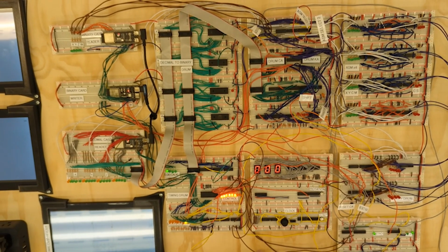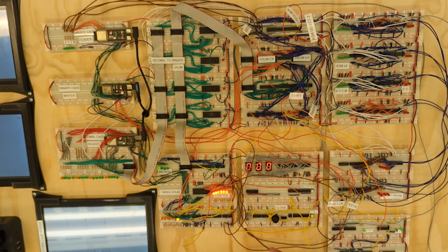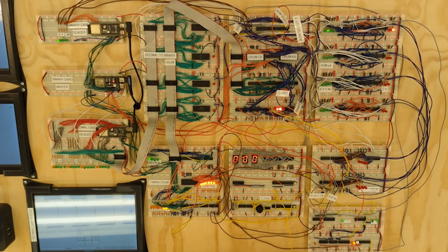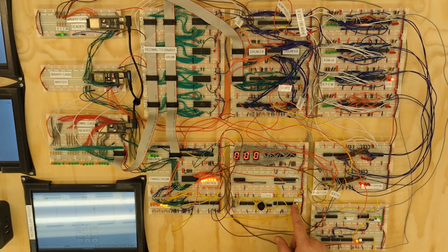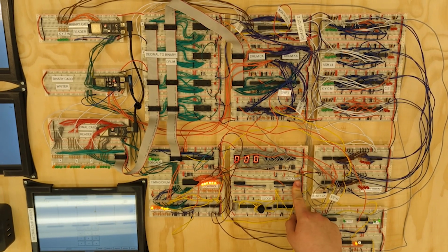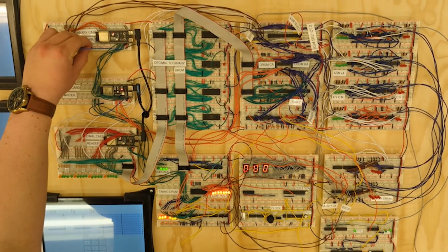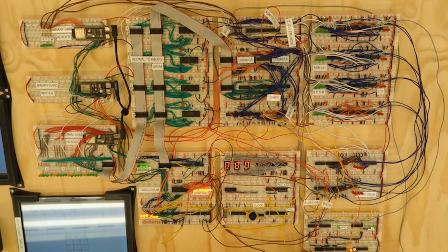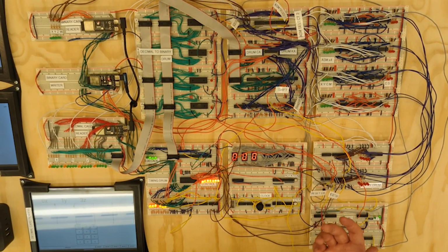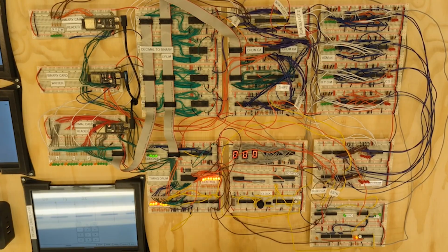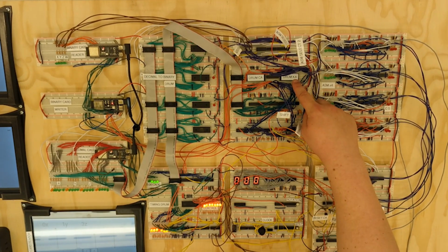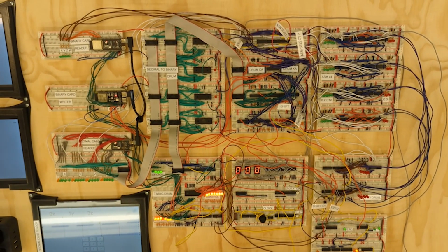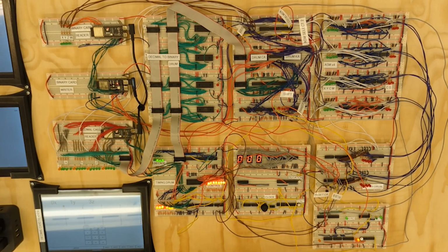We can step through and see that at address 0, we have nothing because none of the numbers have the first bit asserted. But then the second one has this bit asserted for 2, then 4, and then 8. We'll go ahead and disable the module after stepping through the full cycle, reset the inputs, and now we're ready to do our subtractions. So for this reduction, we have 4y loaded in CA, 1y loaded into KA. So all we need to do is just subtract KA from CA 4 times to reduce that y to 0.